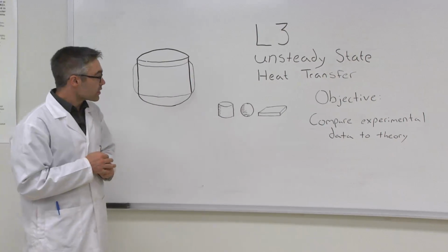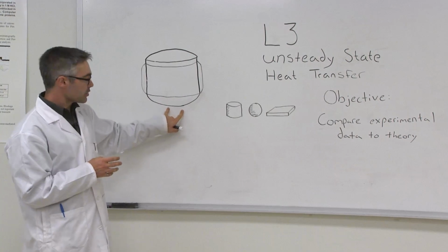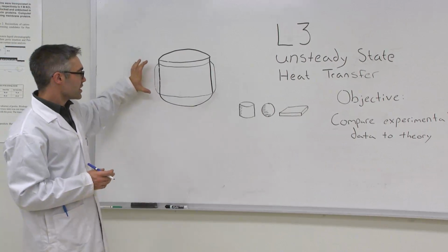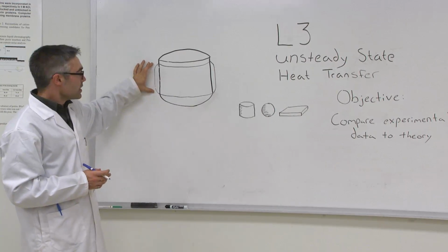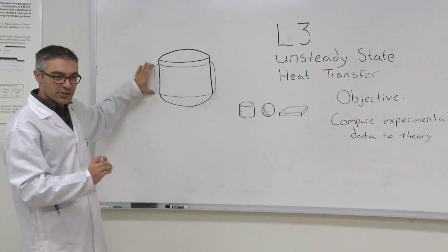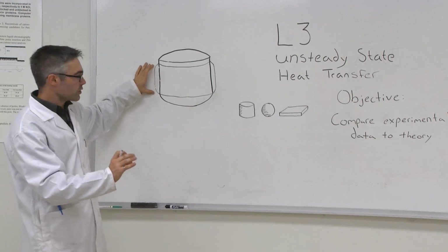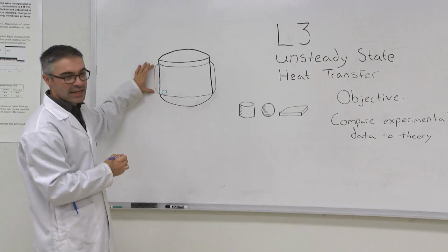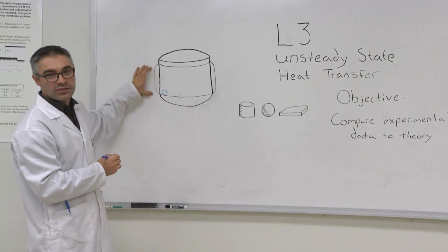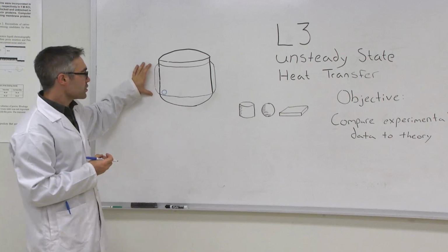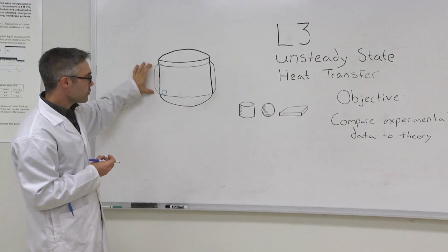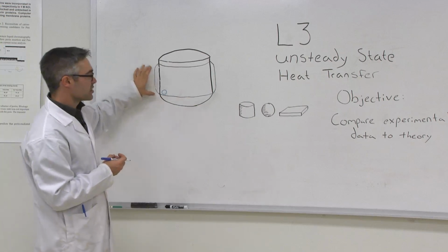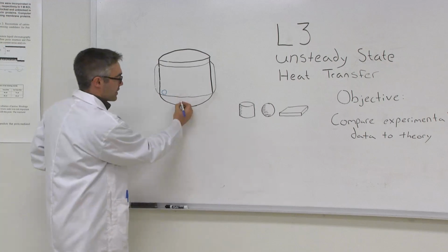So, the way that we're going to achieve this is downstairs we have a large 30-gallon kettle. It's a steam kettle. The steam will be generated within the jacket of the kettle automatically. The steam pressure will be recorded on the wall of the jacket. You'll be able to read the temperature and then ascertain the amount of steam, assuming saturation. This temperature gradient from the steam jacket wall to the water within the kettle will be more than sufficient to keep the water boiling at 100 degrees.